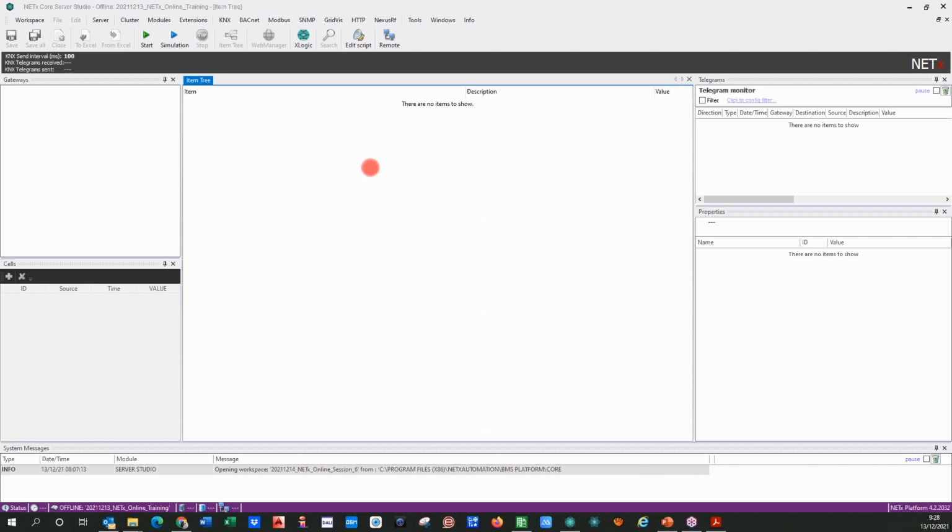You can manage all these windows, close, open, no problem, and also go to the Windows menu and restore the panel position. So it's very easy to configure. But the most important for us is the central panel, of course, and it is very important to handle this properly and to integrate the different protocols. We have the most important options in the main menu toolbar. For example, for KNX, the first option is to import directly from our app file. So I will show you how to export from ETS in order to get this information in our BMS.